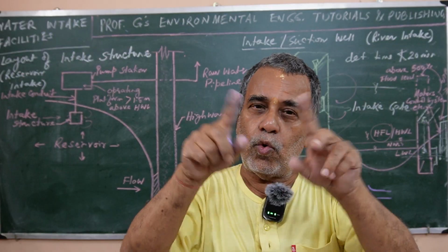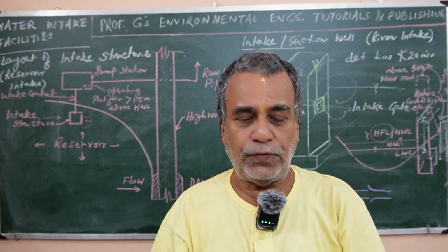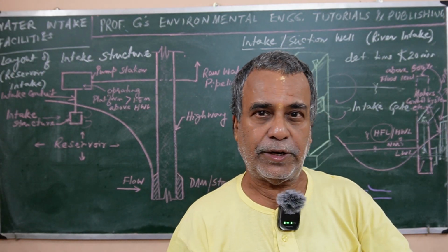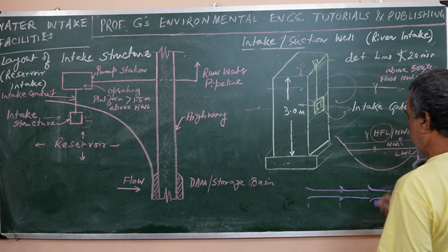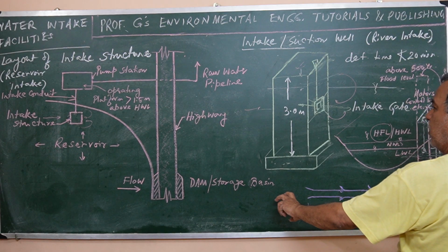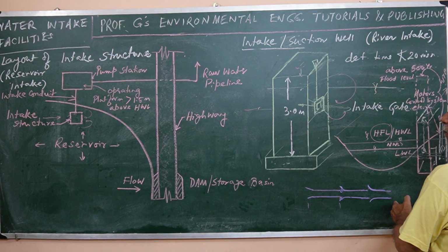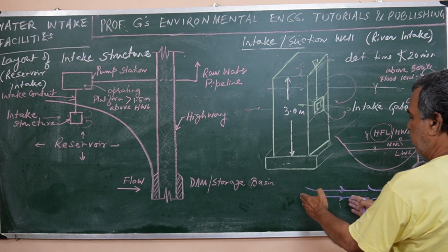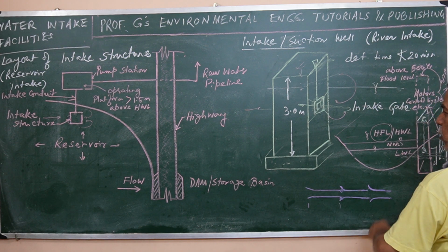Depending on the diameter, O-rings are used, and this is slid to fix into the next part. That is how it is jointed. Here also it is the same, and the required length is made by jointing many pieces of pipe according to the requirements.